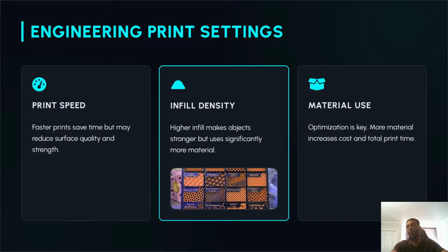You can't have both. Well, sometimes you can, but it's unlikely that you'll have it every time. That's what I mean by depending on how fast your print is going. If it's a complex part shaped in a weird way, or it has a very unique geometry or a unique shape, I would not advise you to print it at 100% or very, very fast, because if you run your printer that fast, you're going to have a lot of print failures and mistakes, and you're going to be wasting a lot of materials.